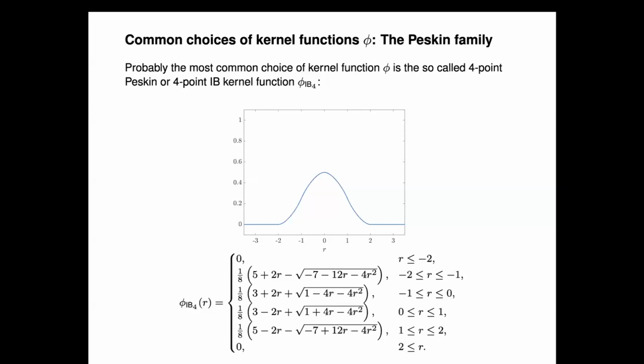But this is the so-called 4-point delta function. The 4-point delta function satisfies two discrete moment conditions that guarantee discrete conservation of force and torque. Something called the even-odd condition, that was originally designed to mitigate instabilities that show up in so-called collocated discretizations of the Navier-Stokes equations, and then a condition that is commonly referred to as the sum of squares condition.